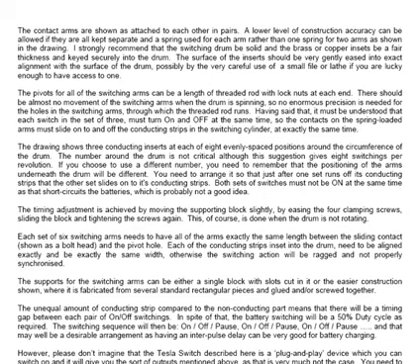Having said that, it must be understood that each switch in the set of 3 must turn on and off at exactly the same time, so the contacts in the spring-loaded arms must slide on to and off the conducting strips in the switching cylinder at exactly the same time. The drawing shows 3 conducting inserts at each of 8 evenly spaced positions around the circumference of the drum. The number around the drum is not critical.